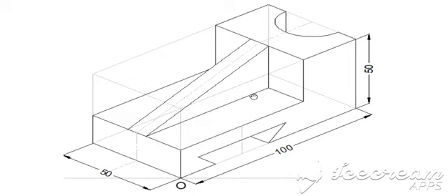At the end, darken the actual edges of the object and give the overall dimensions. Here you can see that this is the L, and in that L we have created the semicircular slot. Also we have shown the H, and then we have completed the rib which is along the symmetric line. We have shown these edges which join that rib to the L, and again we have removed the back edges as they will not be visible due to this rib.